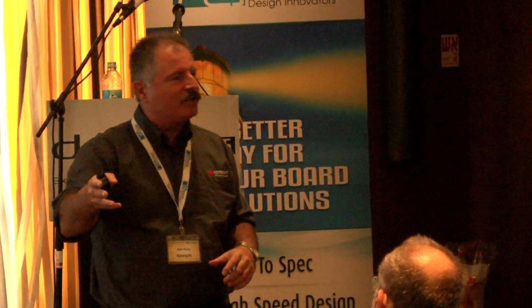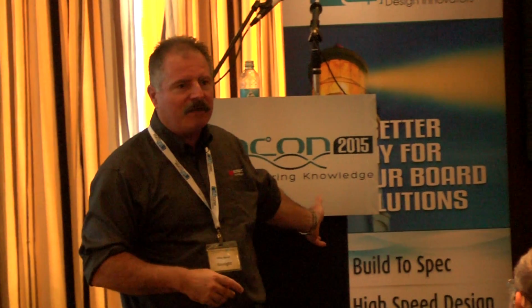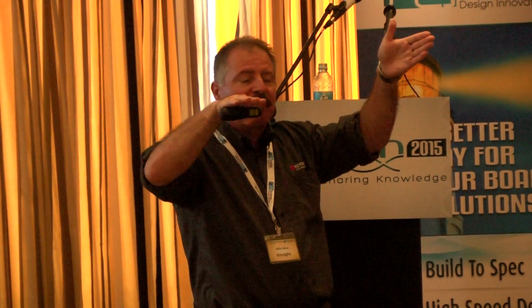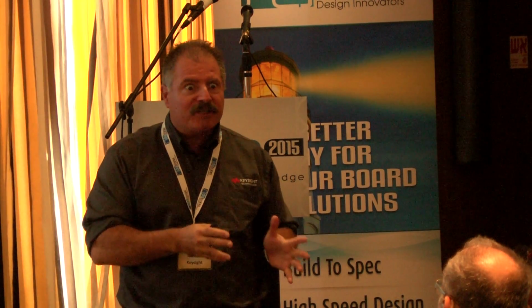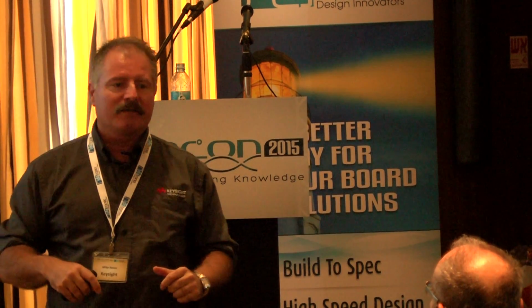This gentleman has an application very similar to the device I showed with 2 daughter cards in a backplane, and he's measuring insertion loss, but he wants to measure it in a vibration chamber. The first thing I would say is don't put the test equipment inside the vibration chamber. Is the wire long enough to get it from outside to inside? What's going to happen is microphonics, which is mechanically induced electrical noise, is going to start to swamp out your signal. You're going to have some vibration isolation between the test equipment and the device under test.